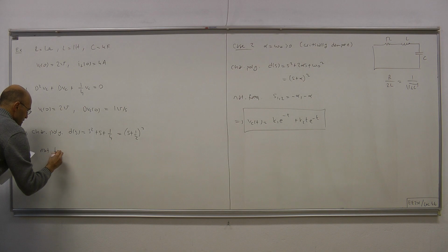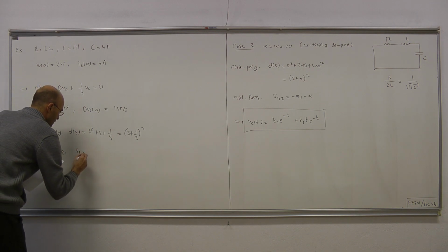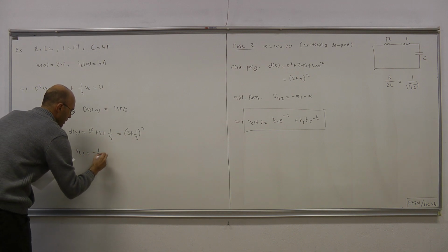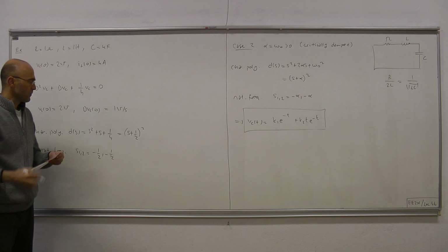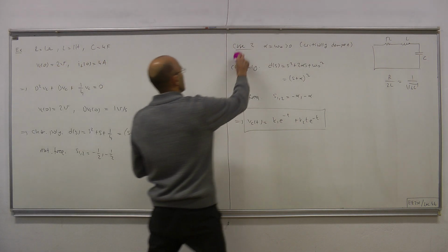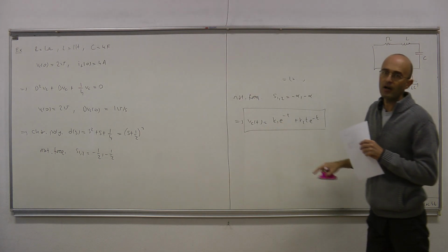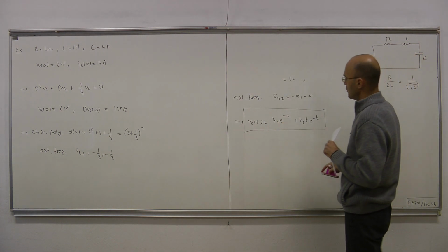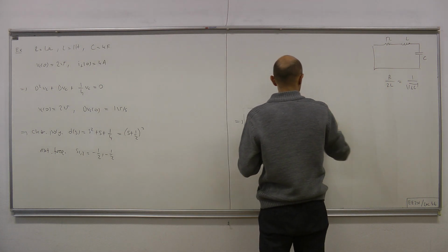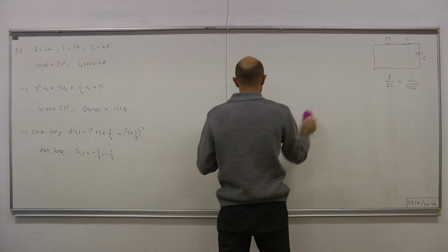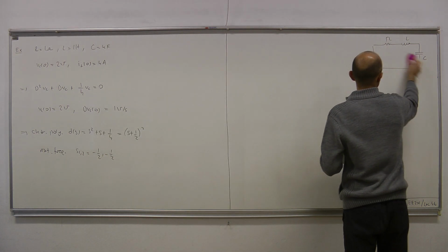So the natural frequencies of the circuit are at minus 1/2 and minus 1/2. Then we can write the solution as k1 times e to the minus t over 2 plus k2 t times e to the minus t over 2. And we figure out k1 and k2 using the initial conditions for the differential equation.